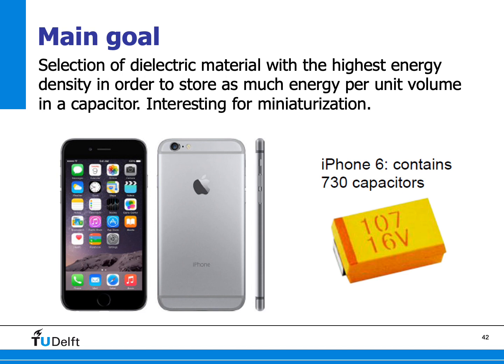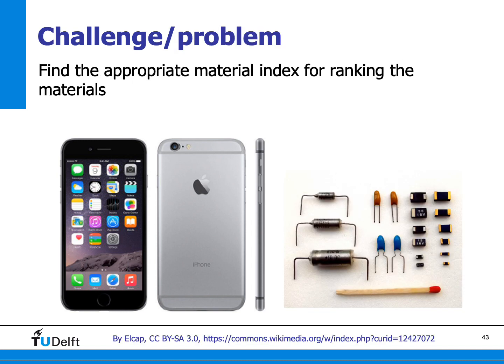So the main goal of this part of the lecture is the selection of a dielectric material with the highest energy density in order to store as much energy per unit volume in a capacitor, which is interesting for miniaturization. For example, in the iPhone 6 are 730 capacitors, and everything of course has to be as small as possible. So the challenge here is to find an appropriate material index for ranking the materials that can serve as a dielectric material for a capacitor.